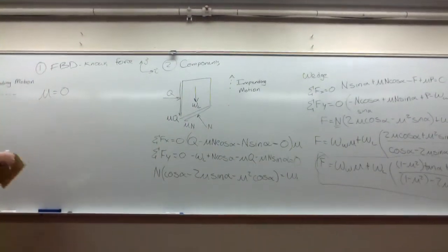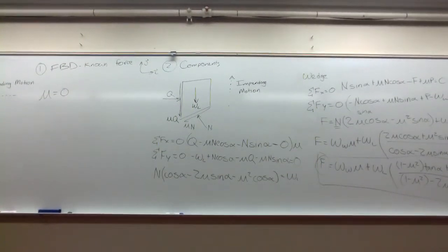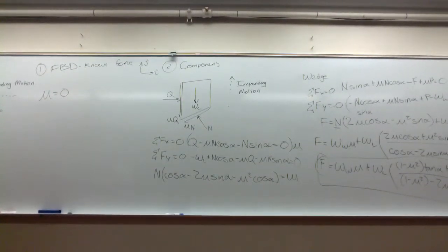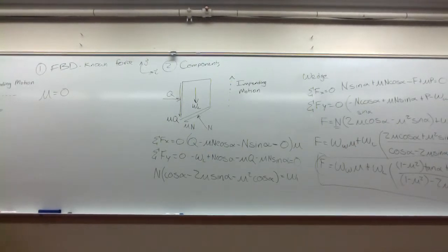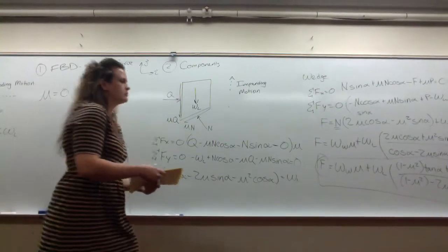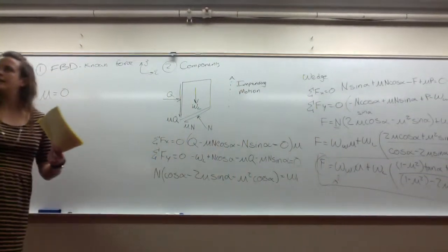You have this small wedge with an angle alpha that's relatively small. For example's sake, we're going to say an alpha of 14 degrees. I measured the doorstop. Our wedge's weight is much smaller than the weight of our load. The weight of a small wooden doorstop in comparison to a door is extremely small, so we will neglect that.